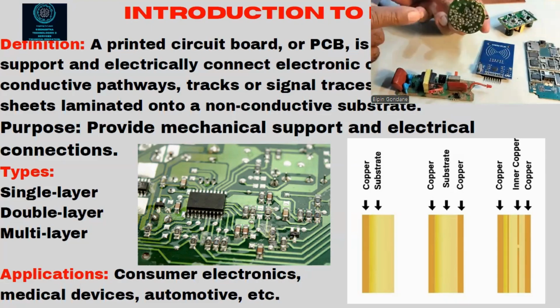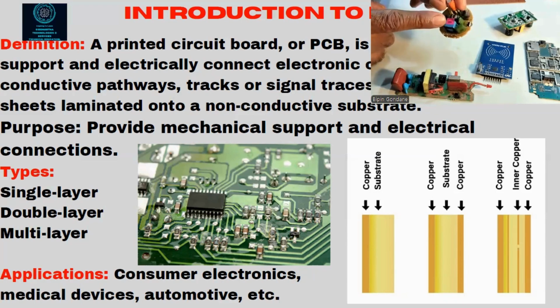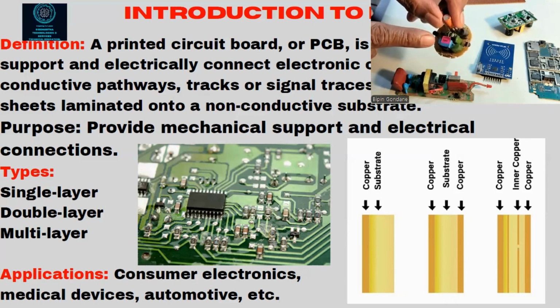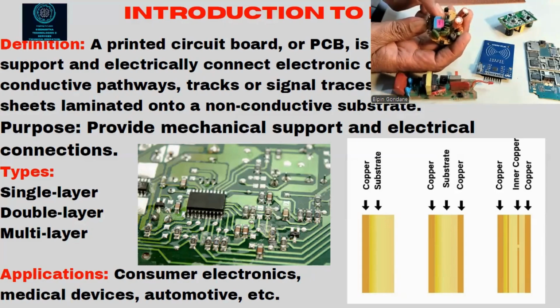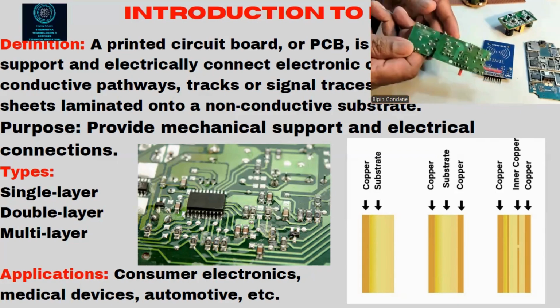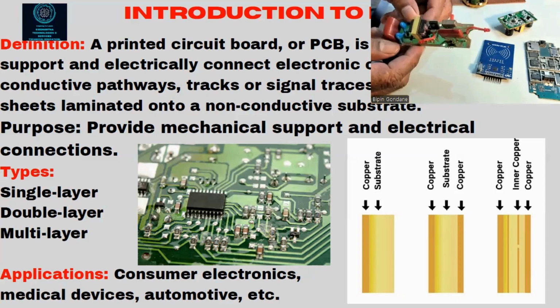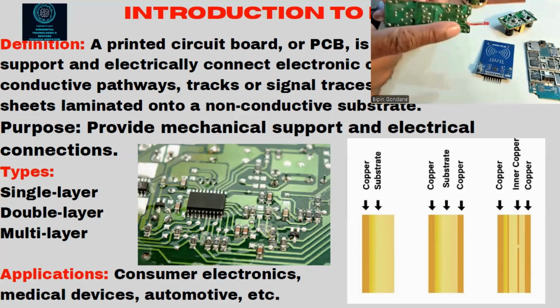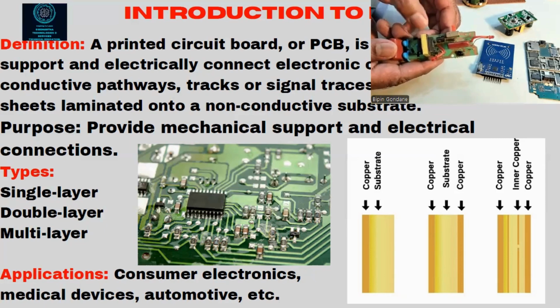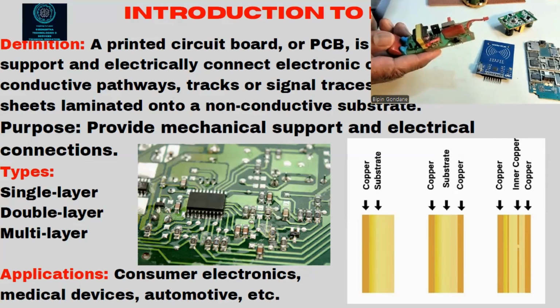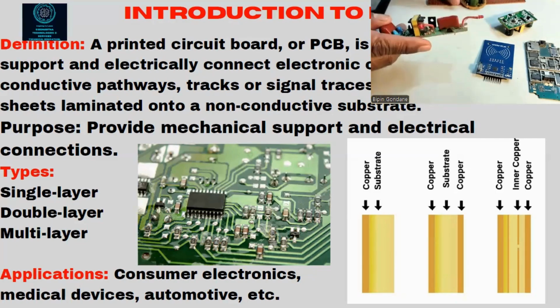I will show you another also. This is also a single-sided PCB because the components are on this side. You can see the components are placed on this side, and the soldering is done on this side. This is a driver, a CFL driver or LED driver, we call it. This is also a single-sided PCB of a power supply, right? Because the connections and the tracks are on one side, and the components are placed on the other side. So this is about the single-sided PCB.